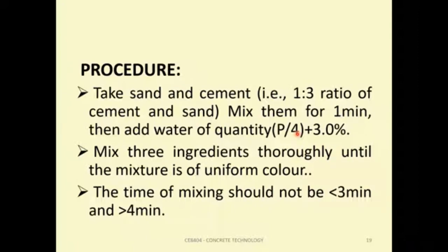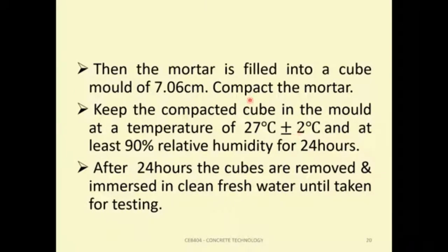The three things are thoroughly mixed until a uniform color is attained. The time of mixing should not be less than 3 minutes and not greater than 4 minutes. The mortar is filled in a cube mold of 7.06 centimeter and compacted. This compacted cube is molded at a temperature of 27 degrees Celsius and a humidity condition of 90%. After 24 hours, the cube is removed and immersed in clean water until it is taken for the test.